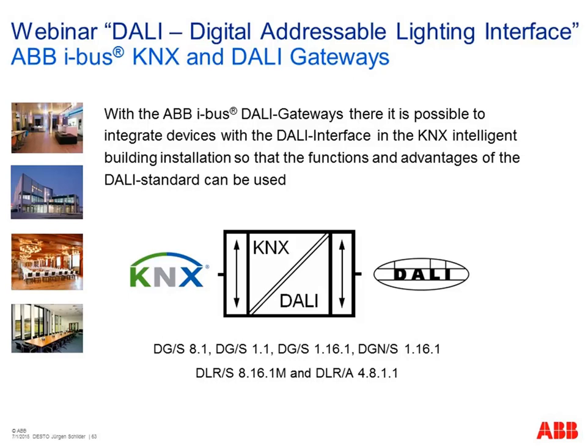So, next step, I'd like to give you a short overview of our existing DALI gateways. You have seen a lot of advantages of such a DALI system. For example, the colored light with all the LEDs, the status messages, the lamp failure, or the ballast failure. And via the gateways, we can send this information into our KNX world. So for different applications, we have different DALI gateways.